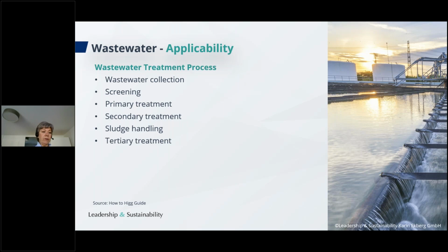And then we have the tertiary treatment. This is maybe similar to how drinking water plants function. The tertiary treatment stage can remove up to 99% of impurities using some of the following techniques: oxidation, electrolytic precipitation, foam fractionation, membrane technologies, for example ultrafiltration, reverse osmosis, ion exchange, adsorption, thermal evaporation. This depends, of course, on the components that you have in your wastewater and what you will then have in that treated wastewater after the secondary treatment and the sludge removal.